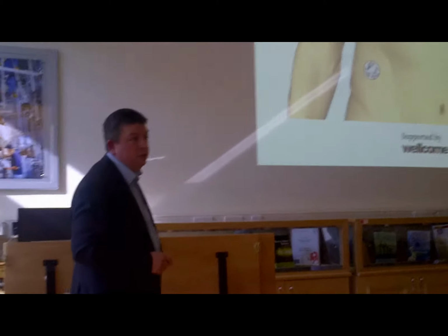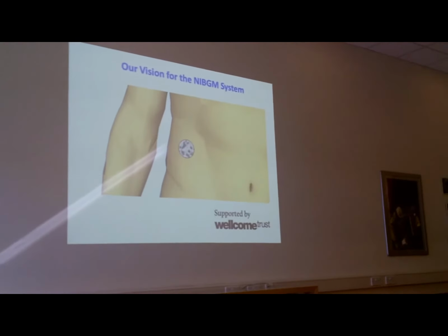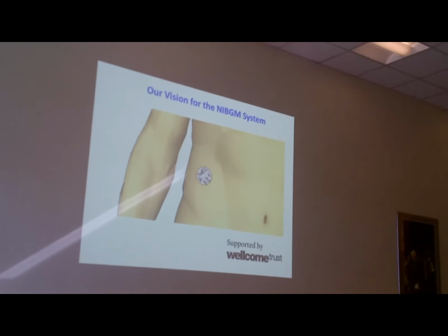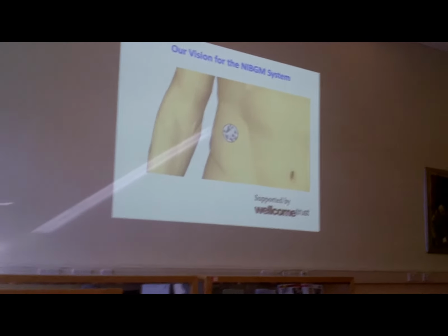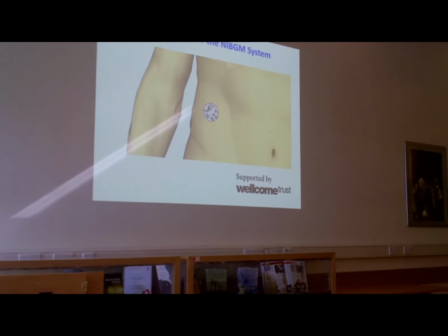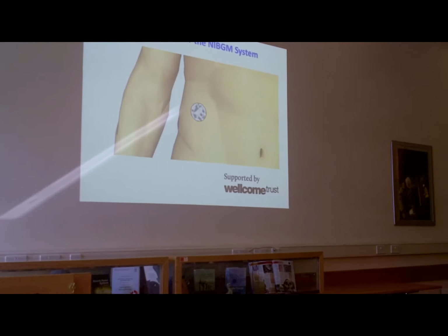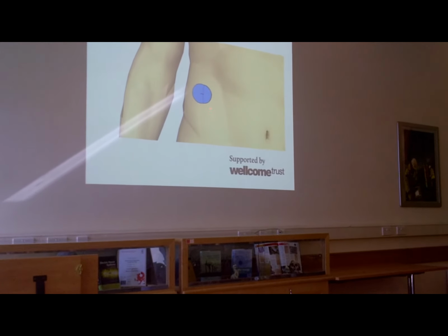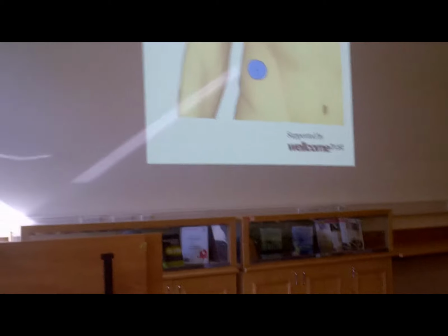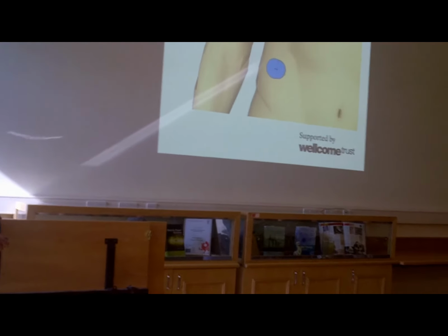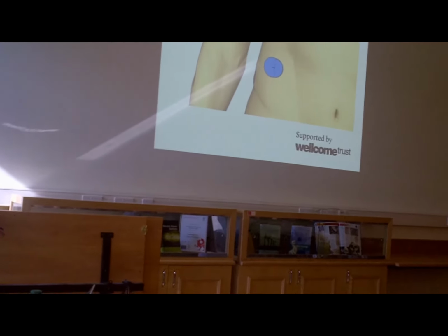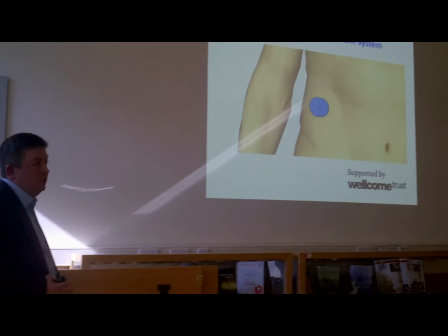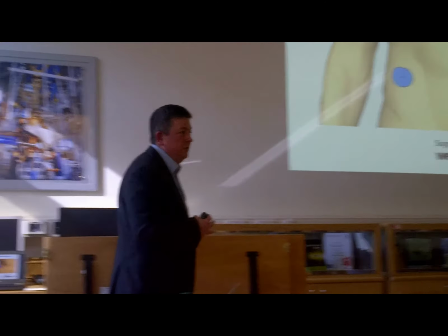So we can quantify glucose in solution. This is glucose in water. Same thing happens in biological type solutions like PBS, for example. If you add glucose to water, two things happen. One of them is you suppress the polarization of the water, and the other thing is that you increase the loss. So there are signatures of glucose within aqueous solution. And what we're trying to do is look at those signatures through microwave resonators that we attach to the body. What we've designed is, this is our vision for the system.